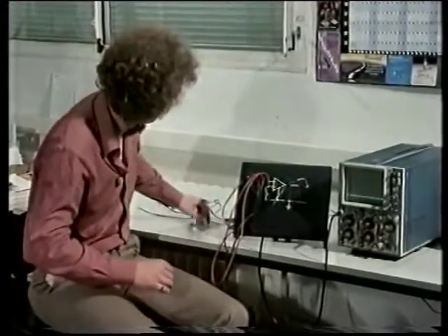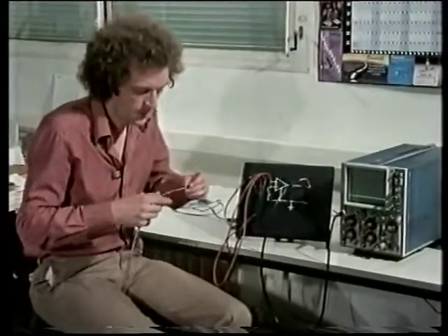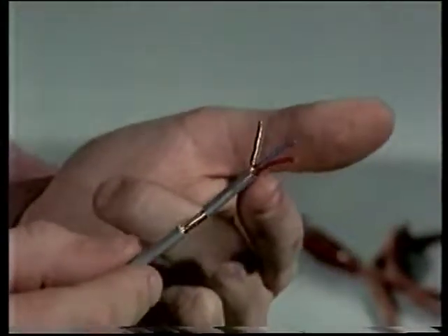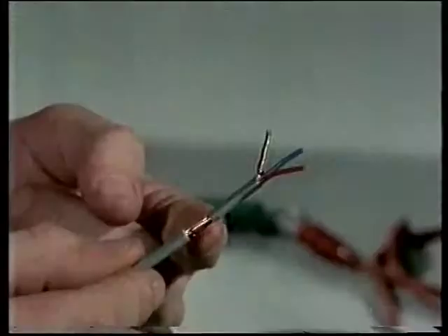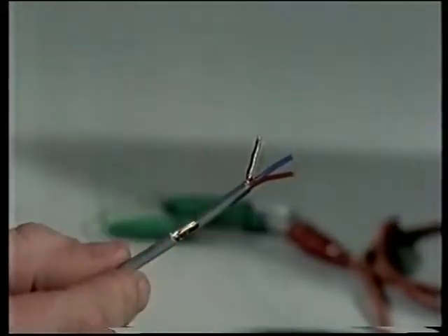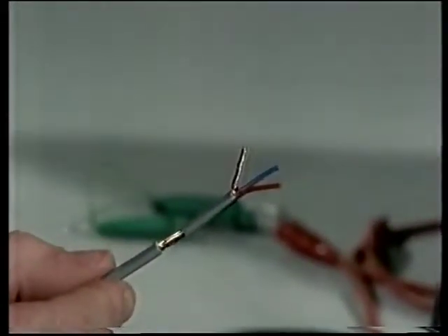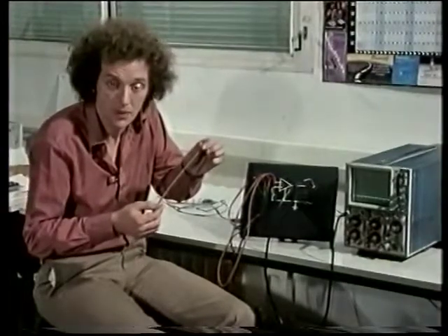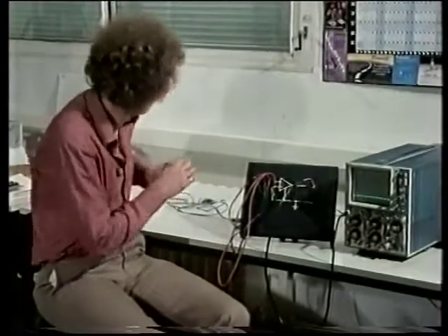There's one further refinement that they use, and that is to use a special cable. This is the same sort of cable. It keeps the two signal wires very close together because it's in the same covering. And at this point here, we've exposed it just to show that surrounding the signal wires is a little copper braid. And this copper braid is brought out here, and it can be connected to earth and screen the cable from some of the effects of the pickup. Let's try that one.